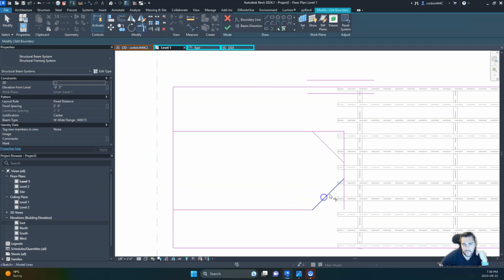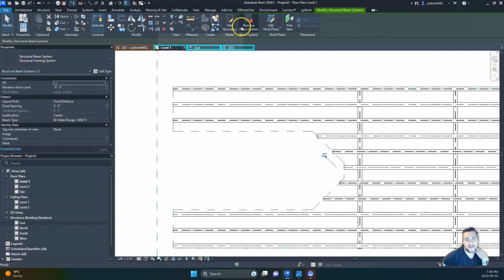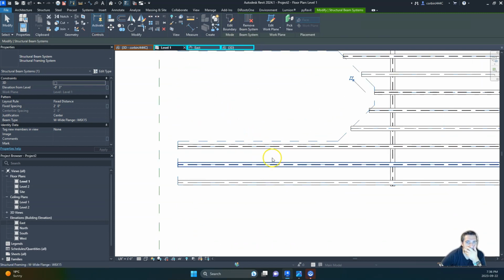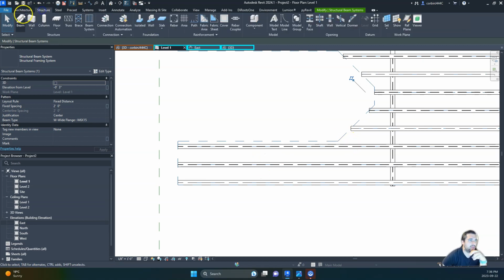And so this is what the boat slip would look like. And so we start by just using the beam system to kind of outline this. And we'll break this piece here. And let's fill it that, and fill it that. Broke the wrong piece there, but it's okay, it still worked out. And so when we click our check mark, it's going to have our pieces kind of going around that dock like that. Depending on what's going on, we might need to make some other adjustments.